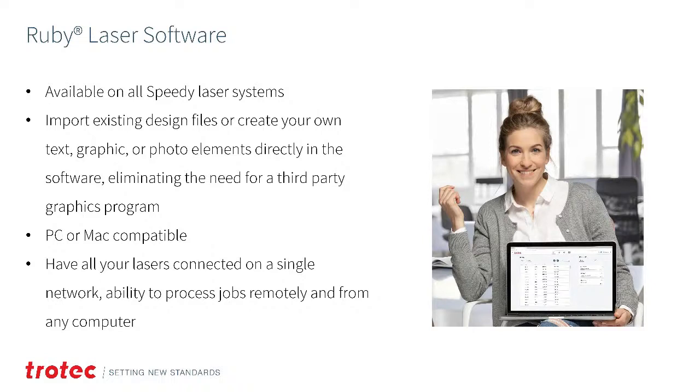In addition, it works with just about any design software. You can run your lasers from Adobe Illustrator, CorelDRAW, AutoCAD, and SolidWorks, limitedly on the 3D stuff. But as long as it can produce a CAD-based two-dimensional drawing that is vector-based, those drawing programs can be converted to formats like PDF, SVG, or AI, then directly brought into the Ruby software and operated.